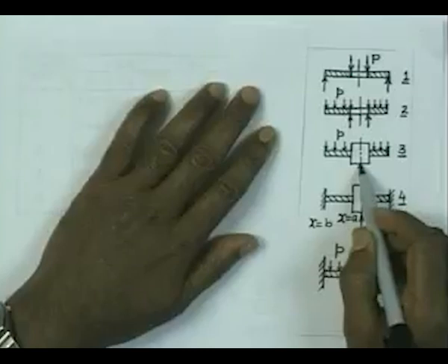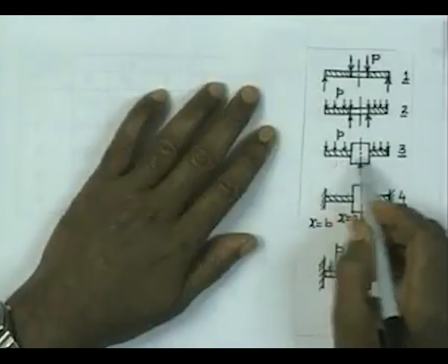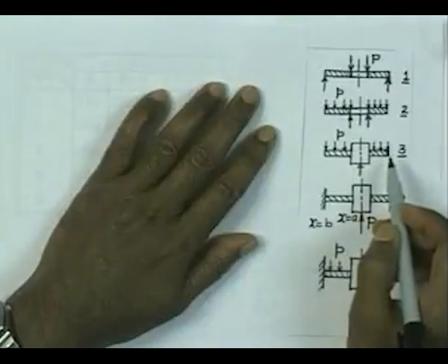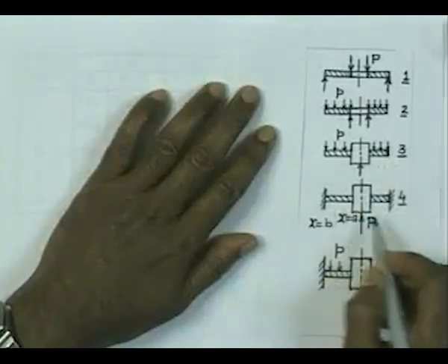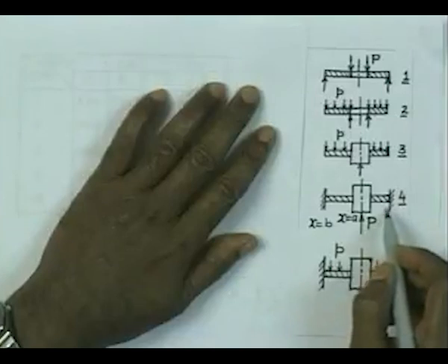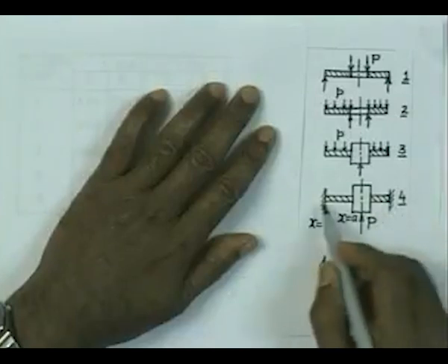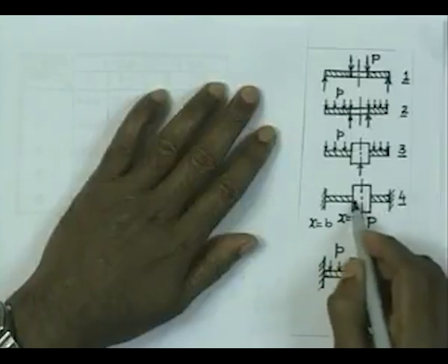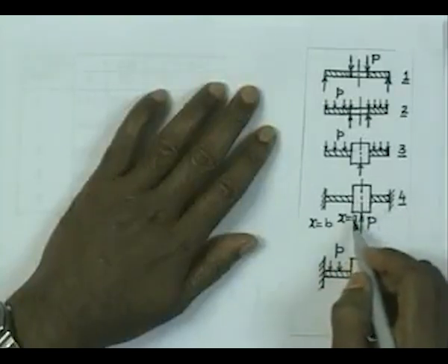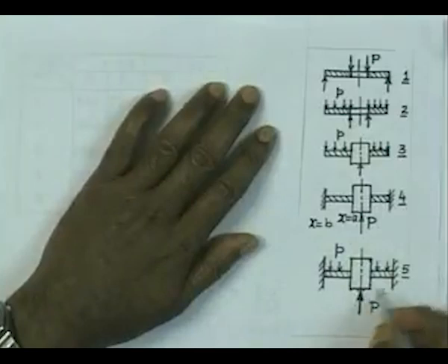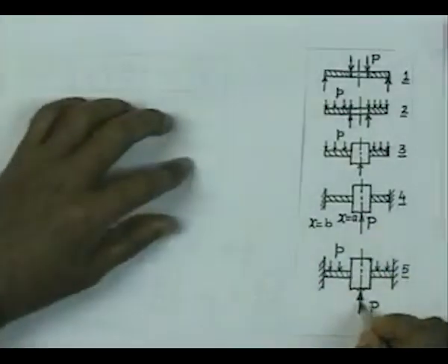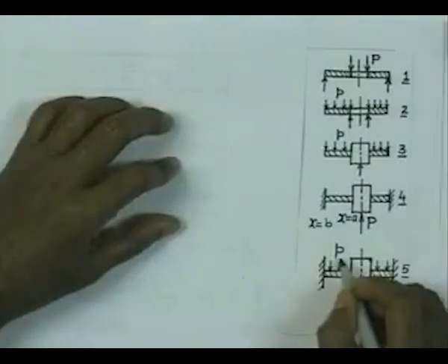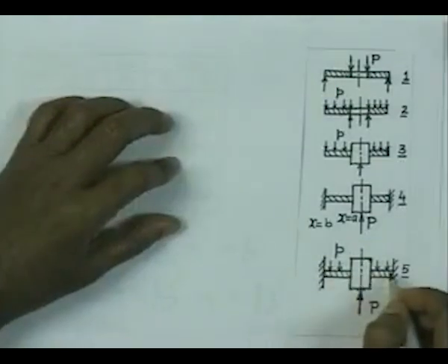Third case is that you have the support at the center through the boss and the distributed loading is coming up like this, and here we have the plate clamped at the edges and the loading is acting at the center through the boss, and the boss outer radius is equal to A. And here it is very similar to that case, but we have the concentrated force here plus the pressure acting at the top.